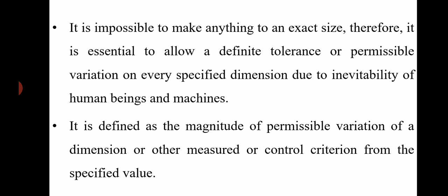It is impossible to make anything to an exact size, therefore it is essential to allow a definite tolerance or permissible variation on every specified dimension due to the inevitability of human beings and machines. It is defined as the magnitude of permissible variation of a dimension or other measured or control criterion from the specified value.